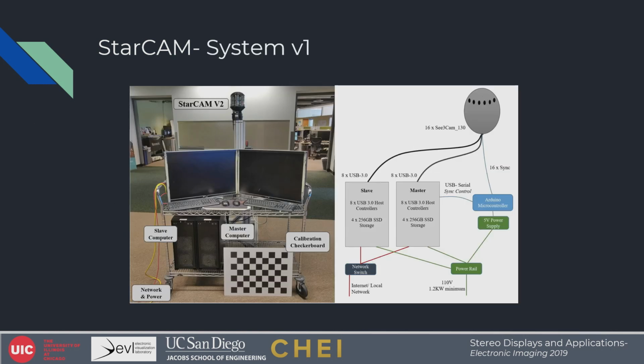The capture system relies on having two computers where each of the 8 cameras go into. We initially started with that because we were dealing with so much data, right? When we're pulling raw images at 30 frames per second from each camera, we were saturating USB 3 host controllers with each camera. Transitioning to onboard compression allowed us to have 2 cameras per USB host controller, but that still required many, many PCIe cards, which is why we distributed it over the system.